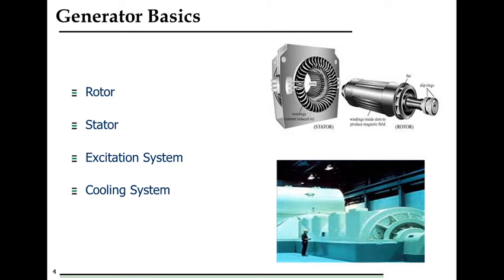Stator core is laminated to minimize the effect of eddy current losses. The lamination is insulated from each other by a thin coating of an oxide and has a space between them to allow passage of cool airflow. The slots are provided in the inner periphery of the core and the armature conductors or coils are assembled in it. The armature winding of the alternator is usually connected in star and the neutral is connected to the earth through a neutral grounding transformer.